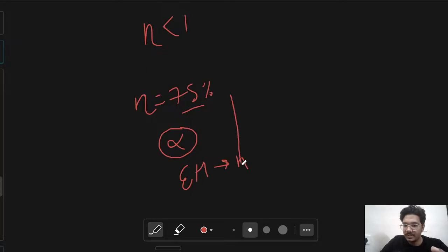Lower alpha means weak absorption, fewer photons absorbed, and eta decreases. Thus the detector material must be chosen so that its absorption spectrum matches the wavelength. Silicon has a high eta at 0.8 to 0.9 micrometer.